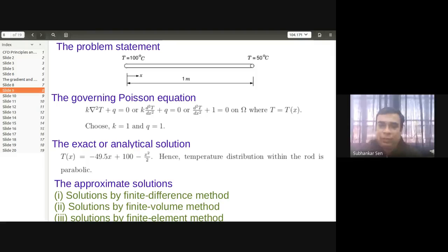This is a diffusion term. Diffusion has the property of elliptic behavior, so diffusion has no preferred direction. When we go for convection, convection has a preferred direction, so in convection you have to use backward difference. But diffusion is independent of direction. It is isotropic. Because of that, you must use the central difference scheme for diffusion.